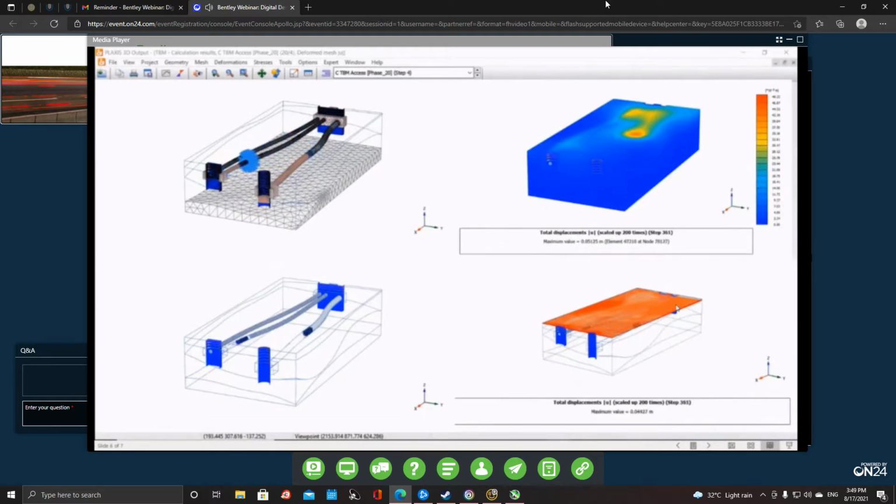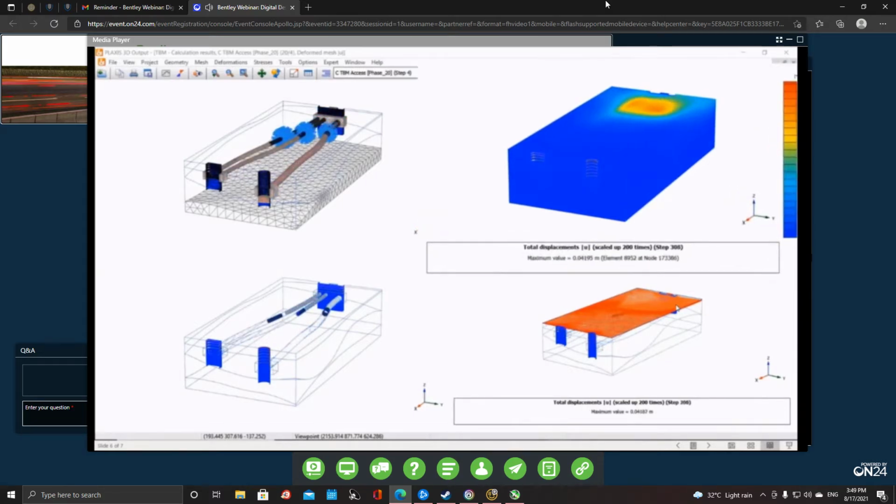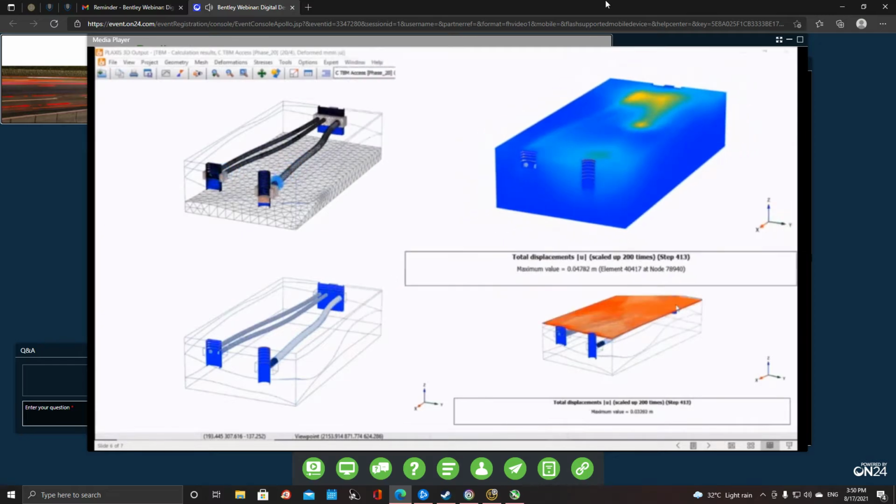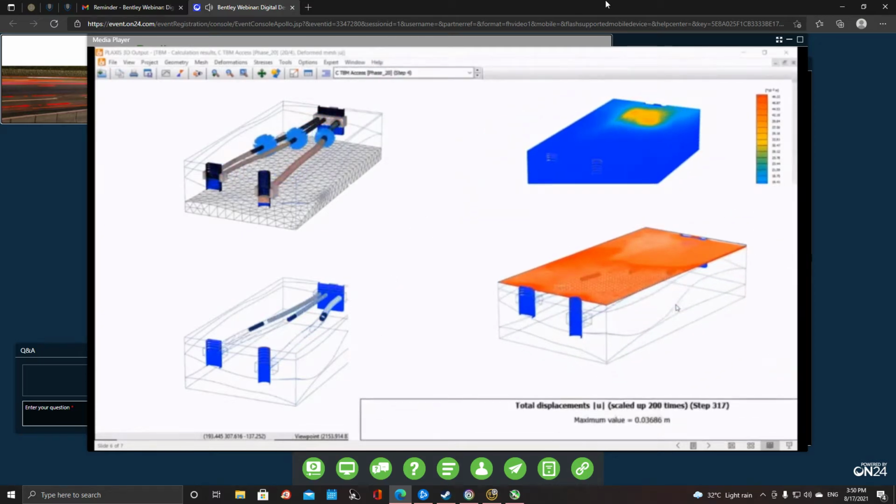High-risk areas are, for instance, the launch of the shield, or breaking out into a shaft or excavation, or the encounter of mixed-face material, like between strong and weak soil, or even mixed-face of rock and soil, where the groundwater seepage could be notorious. Ground improvement is often carried out in the launch and docking area just to ensure the safety during the event of TBM breaking and docking.